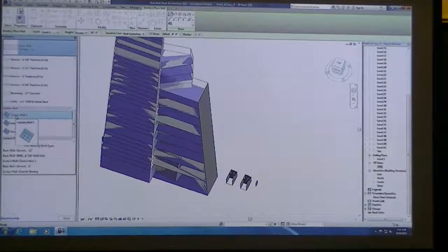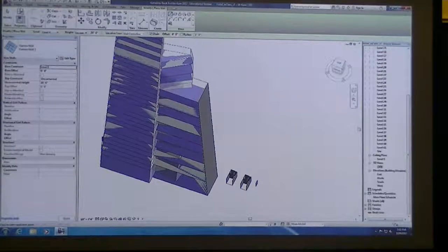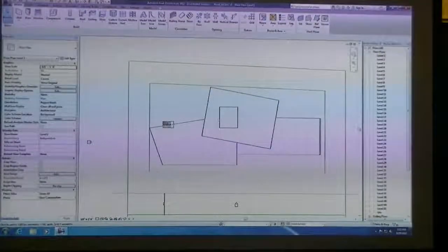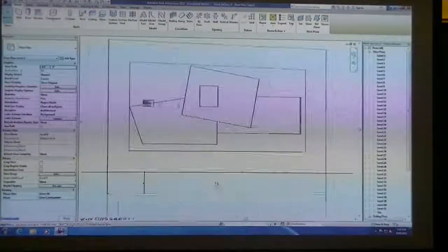Curtain wall basically draws a sheet of glass, and then you divide it up however you would like it, and then apply mullions to it. So the curtain wall gives you more flexibility in actually designing a system that you could actually call architecture and go with a design. So I'm going to always suggest using curtain wall. And first of all, I'm just going to draw this without worrying about our hotel at the moment. I'm going to draw it off to the side.